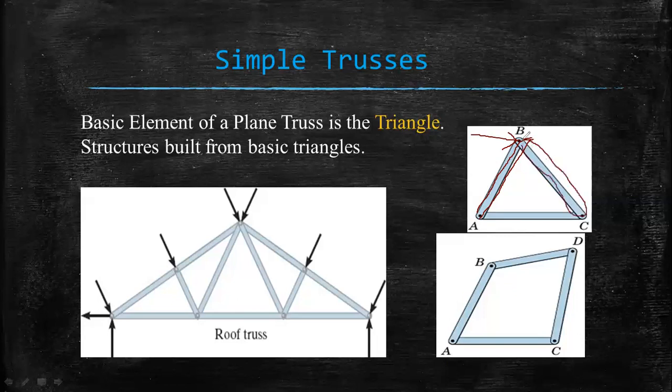And as you know, if you take one steel section and try to deform the body in the axial direction, it is a very tough job, because steel structures generally show a greater strength while you are trying to pull it apart, or provide some sort of compression. So it is very tough to deform one particular member axially. That's why the triangular shape gives a very considerable contribution to the strength.